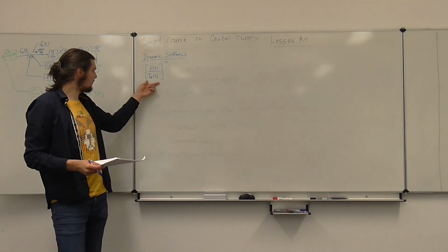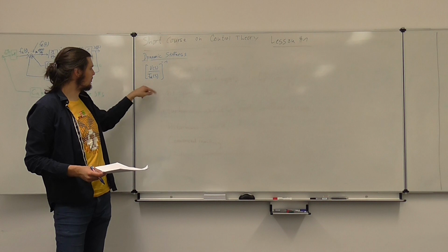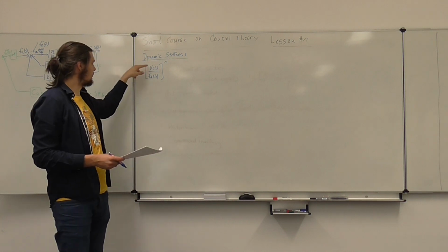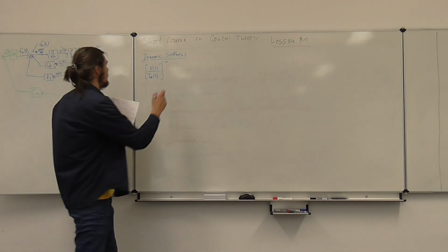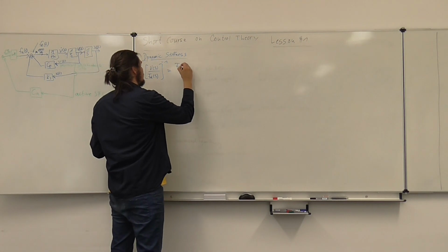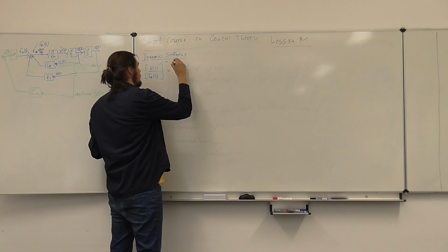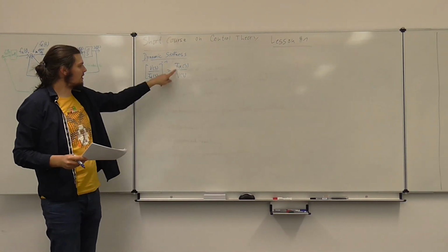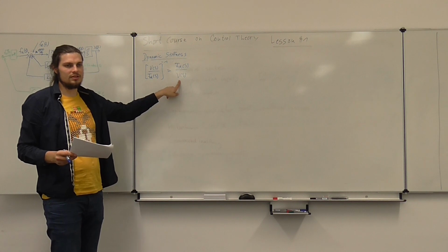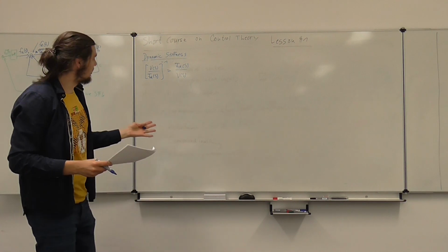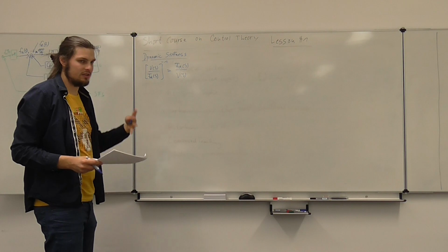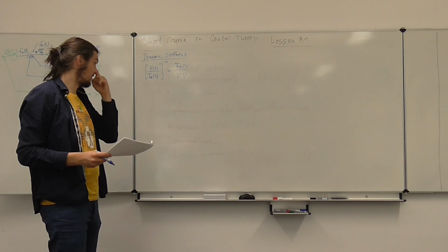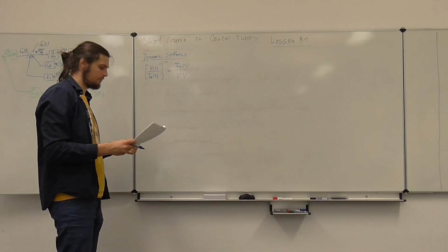So if this value is really, really big, that means you need a lot of force, that's the inverse, right? You need a lot of force. This helps to see this. So this value is very big, you need a lot of force to change 1 unit in the state, right? So big dynamic stiffness tells us we're really stiff in regards to that disturbance.